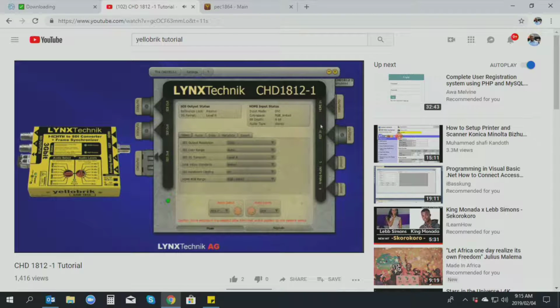So the sending device then scales its output to 720p, sends us a 720p signal, which we then convert to a 1.5 gig output. So that's the way you can jam the operating resolution and get rid of this automatic negotiation, which can cause problems in some applications.